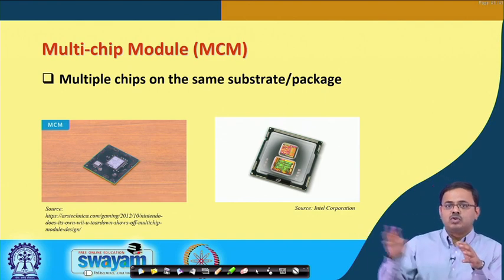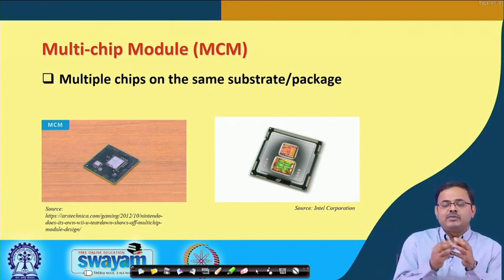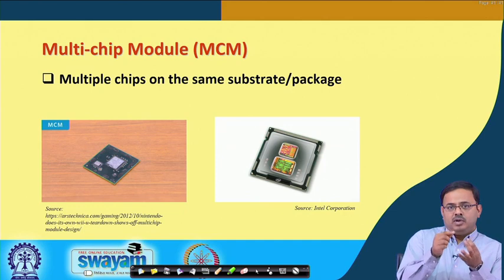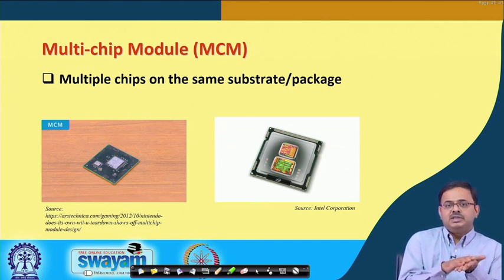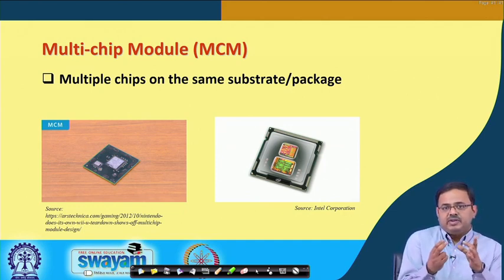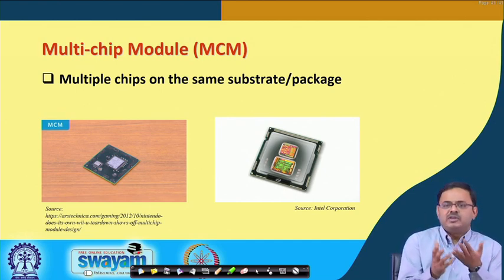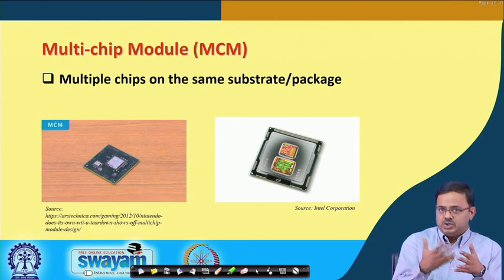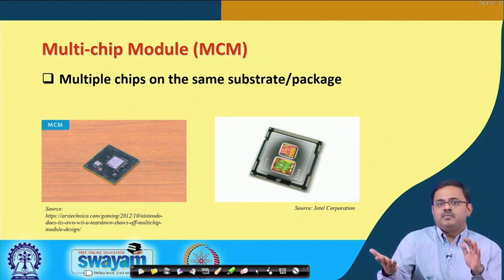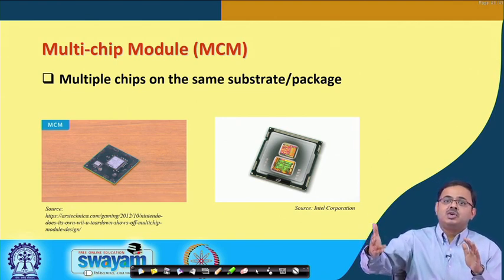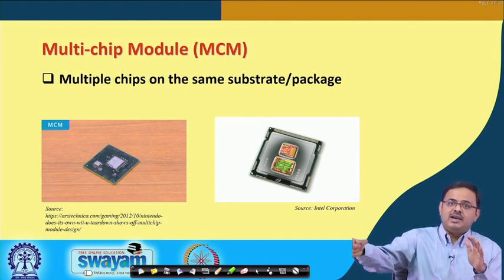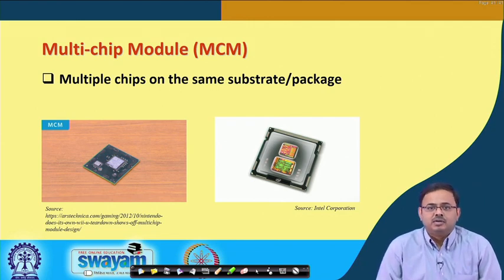If the CPU has to talk to graphics, the signals have to pass from the CPU and the silicon bumps in the BGA onto the substrate, wiring traces on the substrate, and then through the socket, whether it is a pin grid array or a ball grid array directly attached on the motherboard, whatever it is, through another layer of interconnections into the motherboard, then through the motherboard and then another layer of interconnections to the substrate of the second die, and then inside the substrate through another layer of interconnect to the second chip, right.